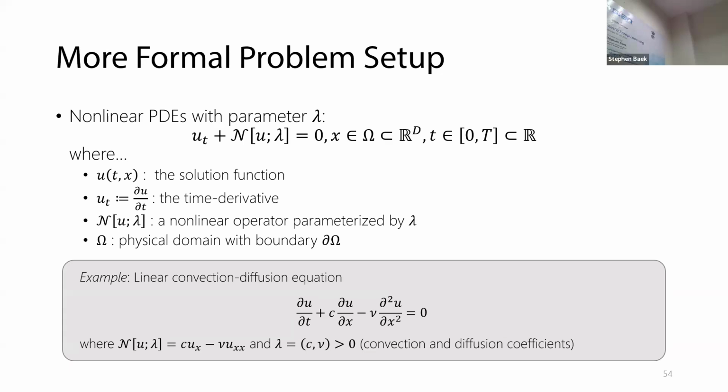So we have the partial derivative of u, okay? So u is the physical quantity that is either diffused or convected. So temperature is an excellent example, right? So partial u partial t, the rate of change of that physical quantity, is defined as we have the first order derivative term, which is the convection term. And then we have the second order derivative, which is the diffusion term. Okay. So C over here is the convection coefficient. And then the nu over there is the diffusion coefficient.